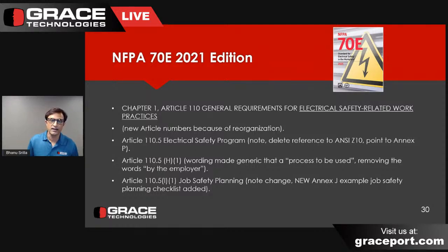So where an electrical hazard exists, you need to make sure the qualified person is the one performing that voltage testing or absence of voltage testing, which we'll talk about. And then 110.9, there was a minor change to cord and plug connected test instruments and cords. Before, there was a different language. That's one of the areas.